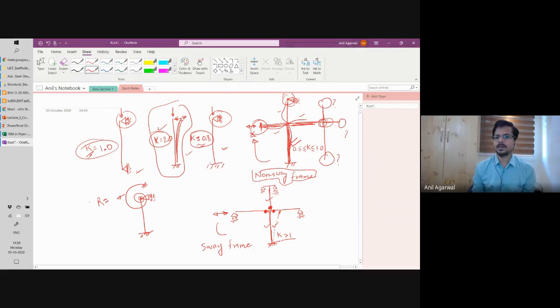See, if the beams are perfectly rigid, absolutely rigid, they don't deform at all, then you will have a value of almost 0.5. At the base, you have full rigidity. At the top also, you might get full rigidity. So the beams have to be very, very stiff and rigidly connected. And if the beams are pin connected to the column, or if the beams are very flexible, the two things are basically the same as far as this discussion is concerned.